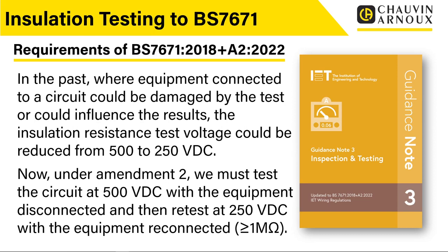Where I think this does call into question a little bit of how this will get interpreted in the real world is when we're doing things like electrical installation condition reports, so where we're testing installations, particularly complex installations, where there's already equipment in service, where it's almost impossible to go around and take out, you know, every piece of equipment from a circuit. One example that always used to be talked about with this is if you've got a socket circuit with surge protected sockets.